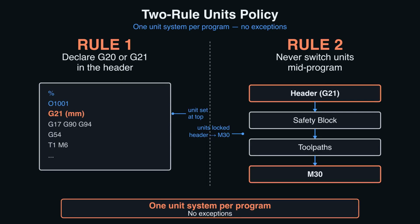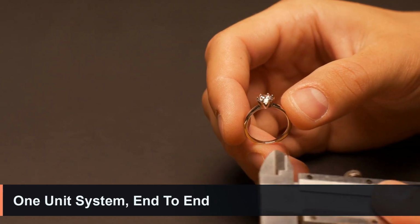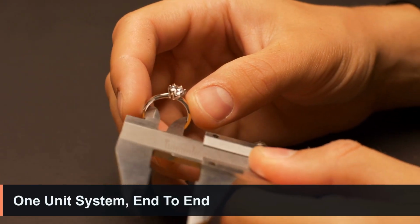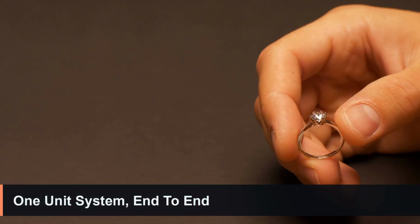So the real rule is 2 parts. 1. Declare units in every program header. 2. Never switch unit modes inside a program. Pick the unit system at the top and stay there until M30. If the part is metric, the program is metric, the offsets are metric, the DRO is metric. Mixing units is how you turn a controller into a random number generator.